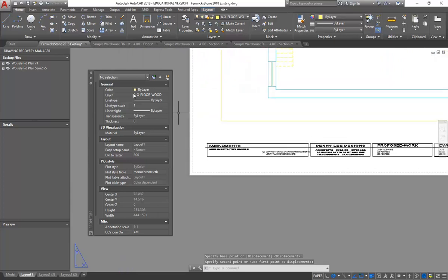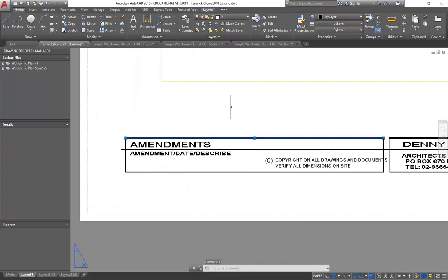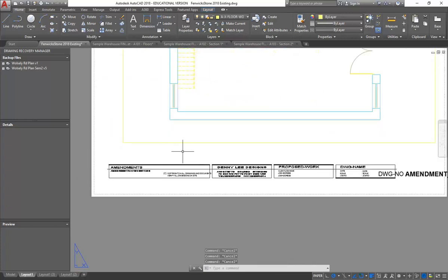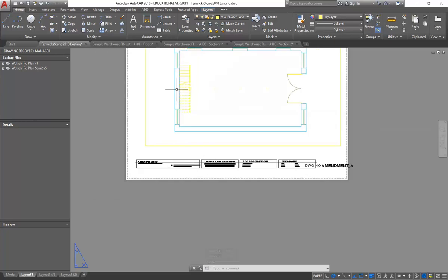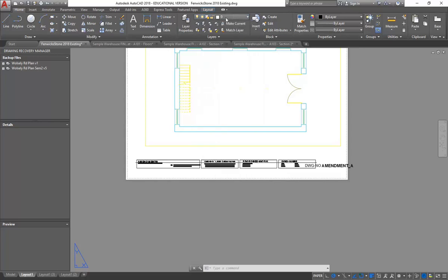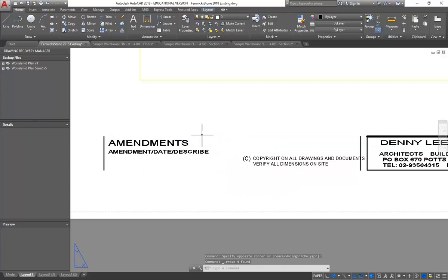Okay, so then, again, don't be afraid to do these lines again. And, oh yeah, and again, if you're going to use this title block or even the other one, the easiest way to draw new things is to put them on layer 0. So I might decide, well, actually, I don't like any of these lines, so I'm going to delete them.